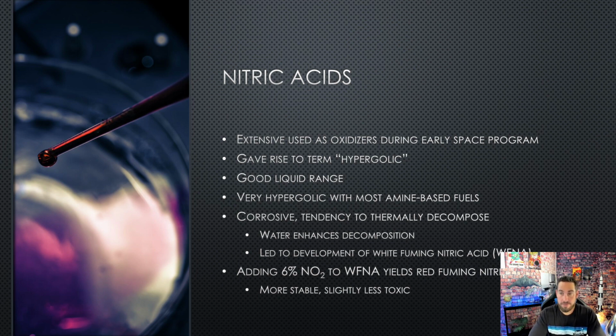Nitric acids have a good liquid range. They're very hypergolic with most amine-based fuels. They are very corrosive, though, and they tend to thermally decompose, so they'll generate a lot of heat. Water enhances this decomposition.